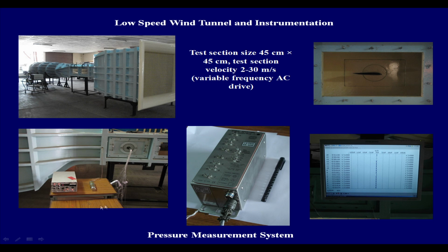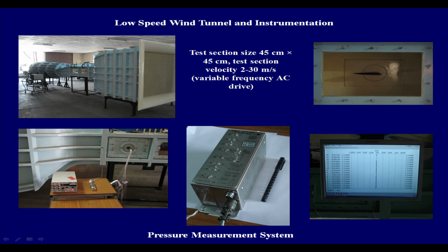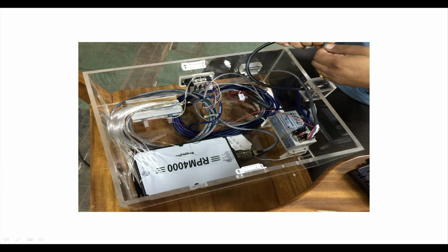This is another variant of this, or rather a more modern version of that pressure scanner here. This is what is called a DSA unit, and ultimately what you see over here is the data being acquired on the computer. This is a still newer unit where, as I was saying about miniaturization of the pressure scanners, which has happened over time. The same scanning valve which was much larger here remained a bit large even in this design, but substantially reduced in size when it came to a design like